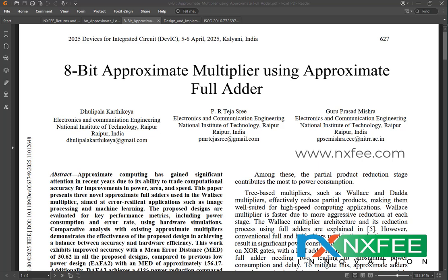controlled error behavior. For that, this work presents a new approximate full adder which uses only the Peres gate and one Feynman gate, introduced to reduce the number of reversible gates, constant inputs and garbage outputs, while confining the approximations to the least probable input combinations to avoid major error propagation.